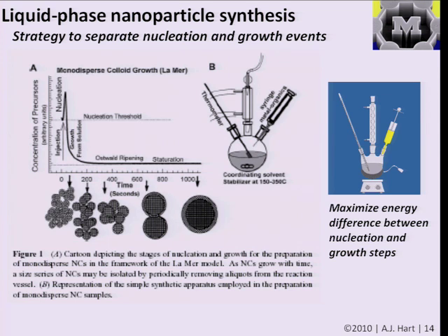And you can grow those particles with a controlled size, but you can also confine the size distribution. The ideal case perhaps being that you grow the particles with time to give you your final size, say 5.5 nanometers, and through that growth process, as the particles get bigger, there are also ways that the process is controlled so they have a narrower and narrower size distribution, so the standard deviation of the particles also remains bounded and as small as possible.